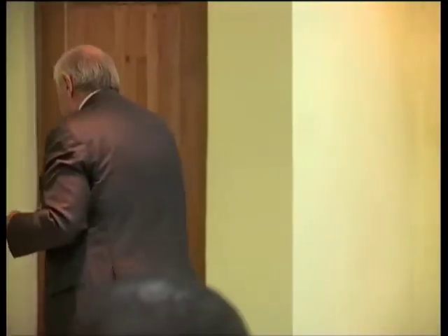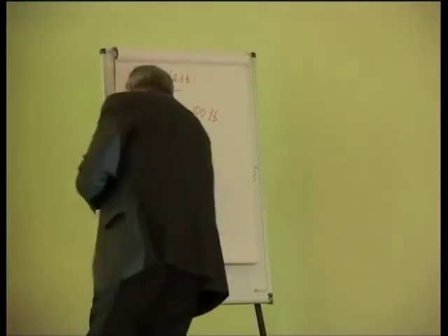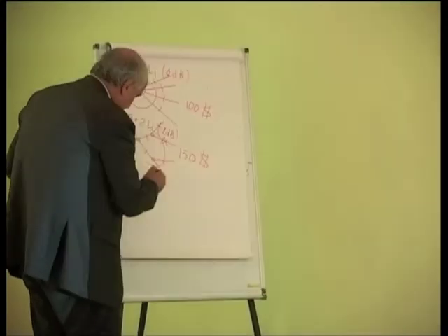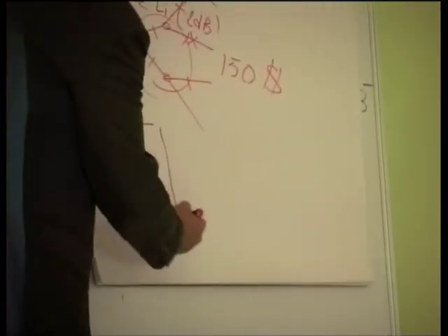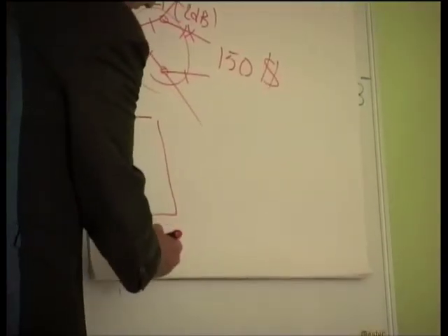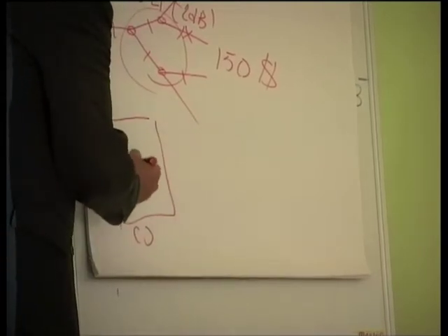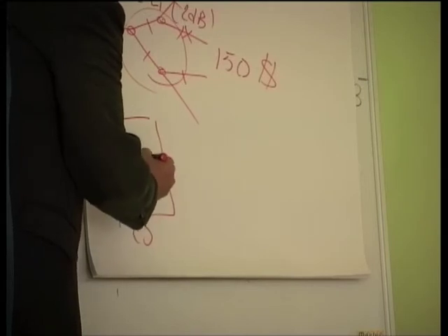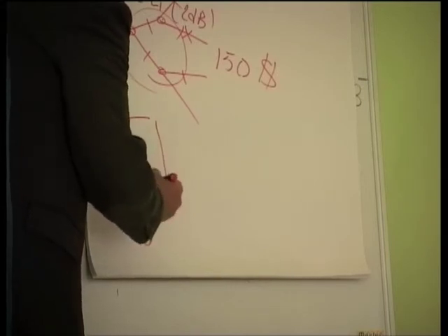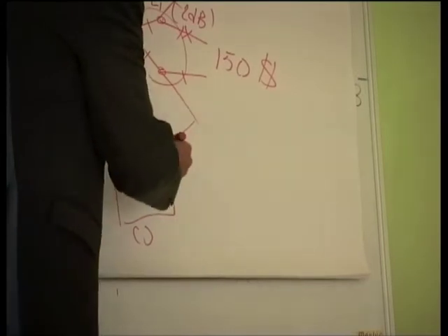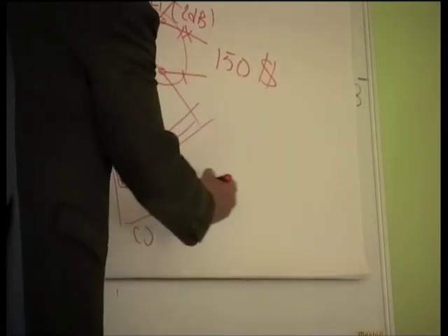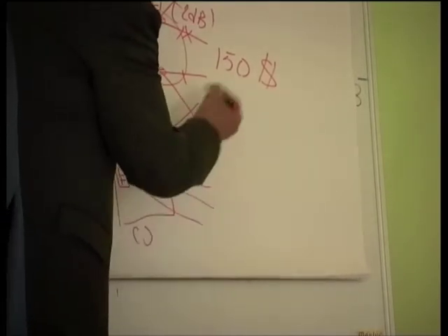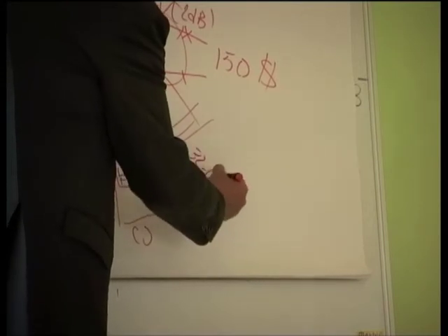But the other way around is that I can put the splitter in the central office. This is the central office. Here I have the OLT, and I have the splitter immediately near the OLT. And I exit directly with 32 fibers.